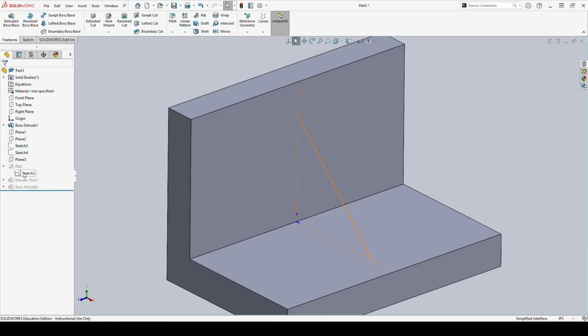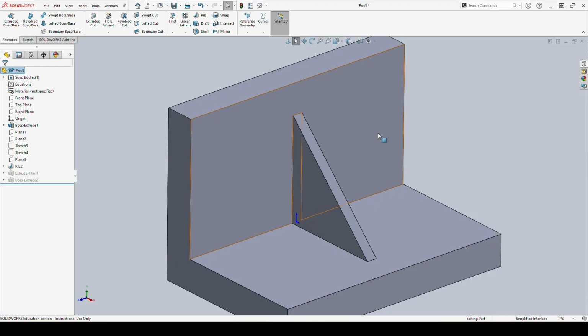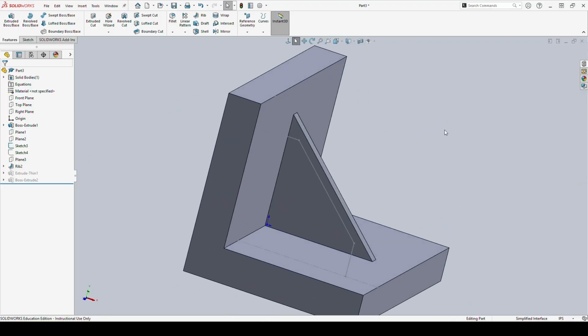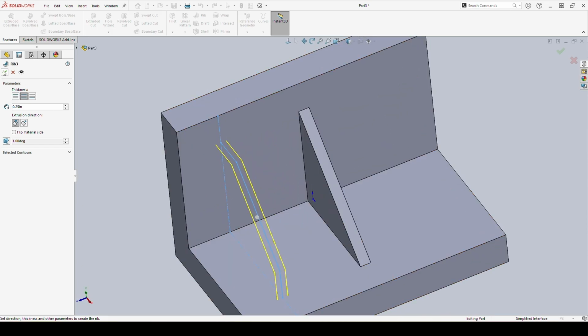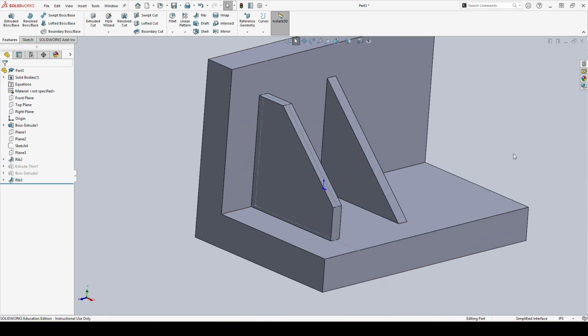With this, what I will say about ribbing is we don't have to always use just this very basic rib shape where it's a straight line. We can use this with a ton of different shapes. So here I have a rib that has a couple straight lines on either end before it goes through the diagonal, and I can use the rib command and that will work without a flaw.